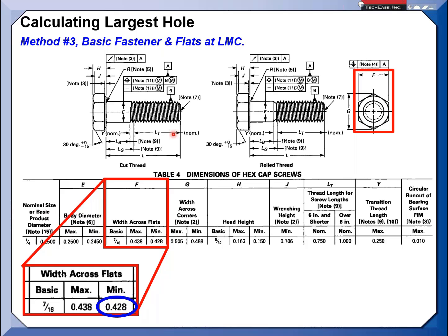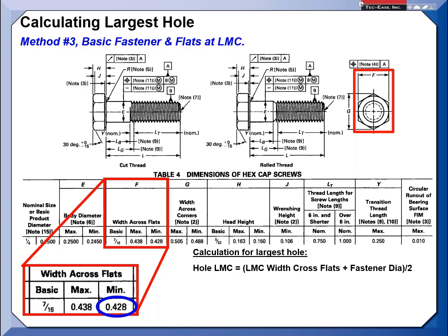There's the right median line, it's bowing a little bit out of straightness. So it's just another way maybe to add in a little cushion that if the bolt didn't come in perfectly straight. So again, these are decisions. So we're going to use the LMC across the flats. In this case, for the actual diameter, we'll use the basic value, 250.